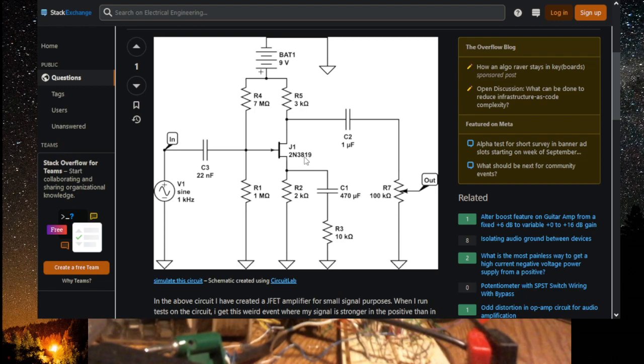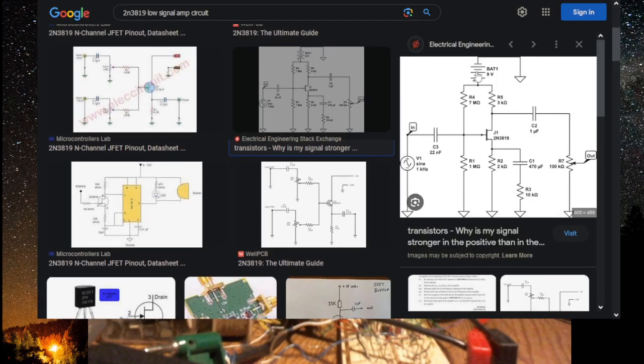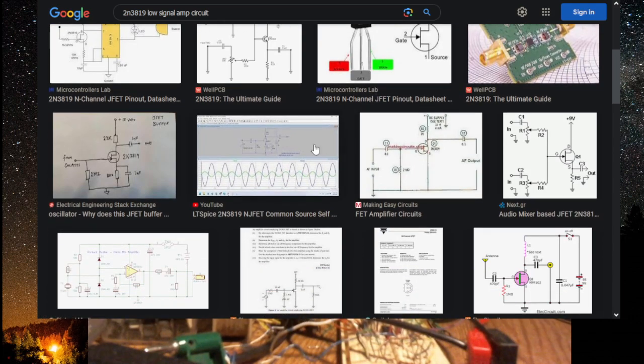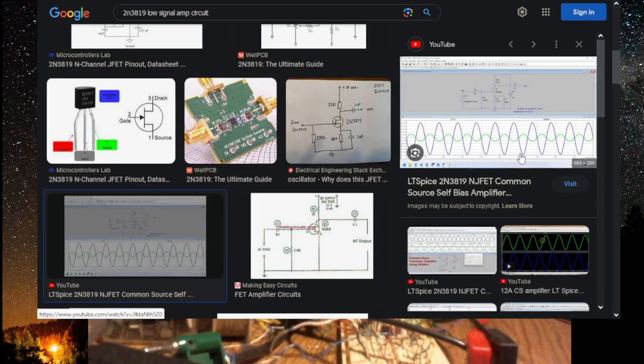That looks like a pretty good circuit. So you've got a 7 megohm and a 1 megohm input resistance. Now, typically, when you have these megohm resistors, they add an excruciating amount of noise to the circuit. And maybe that, because this is fed back on this plus line, it could be the amplification section and the gain section here. This is a circuit that somebody built, so let me just go through here and see what this is. This looks interesting.